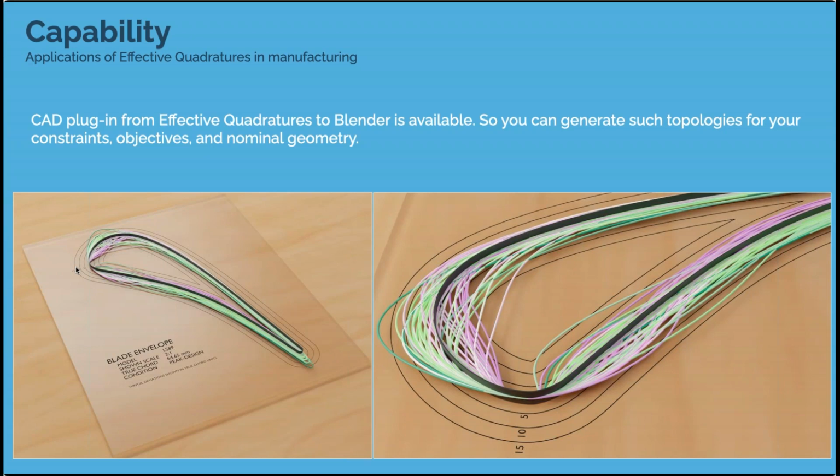And the hope is that for future compressor and turbine designers, if they wanted to understand what the impact of manufacturing is, what kinds of tolerances they should impose on the design in terms of manufacturing, they could literally 3D print a blade envelope and have it sitting on their table, and they could study the distribution associated with the envelope. This is something that we shared as well with Rolls-Royce, and they were really happy about this. They actually want to generate such envelopes for in-production blades, just to understand the impact of manufacturing variations. So this is something we're really excited about. But yeah, the code's all open source, so feel free to use this on your own test case as well.